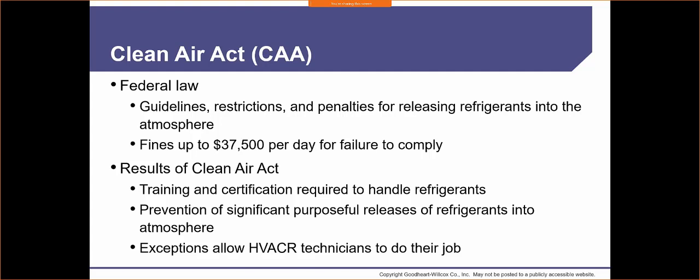We need to get the old refrigerant out of our lines because I just worked on a 410A system, or our hoses, I should say. We're not going to hook up our 410A hoses filled up with refrigerant into an R22 system. So I have to release all that gas out so that I can work on a 22 system. That's acceptable. Going up to a unit, cutting it, releasing all that refrigerant is not.